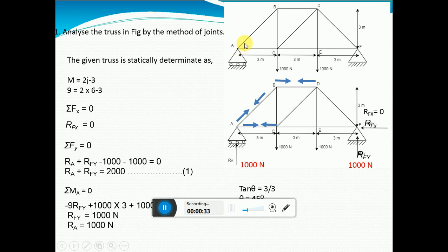So this is the truss given, and here is the roller support, a triangle, and the rollers here with the hashed surface represents a roller support. You have seen in the chapter of supports and reactions. So here this is the pinned or the hinged support.